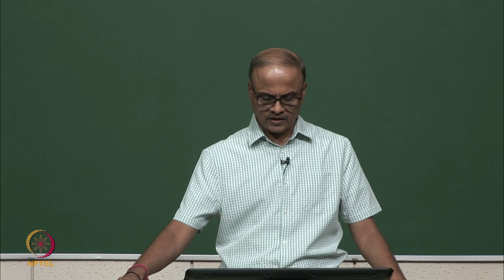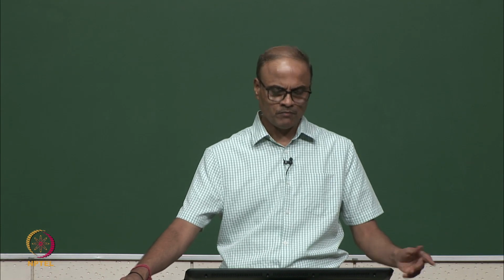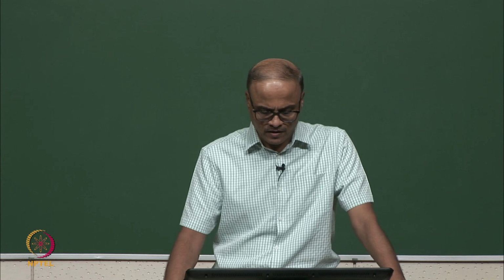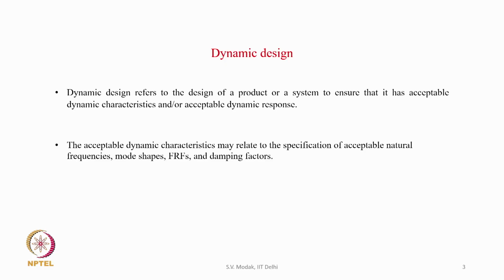Now what are acceptable dynamic characteristics, and what do we mean by acceptable dynamic response? The acceptable dynamic characteristics may relate to the specification of acceptable natural frequencies, mode shapes, FRFs and damping factors. For example, there may be a requirement that there should be an absence of natural frequencies in a certain band of frequency so that resonance could be avoided, maybe because the excitation forces predominantly act in that band of frequency. This could be one requirement.